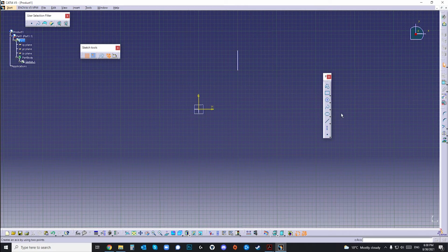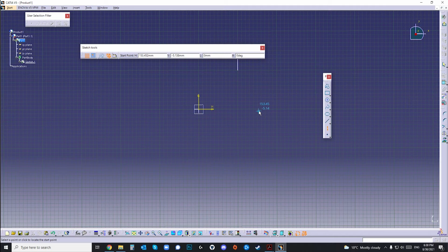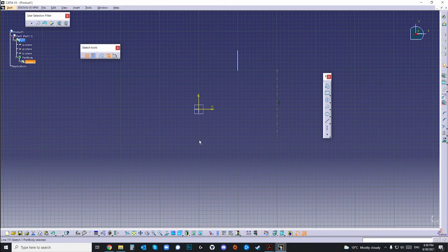In the same manner, you can dimension the axis, and with the point you have just two coordinates because we are in 2D. So if I press for horizontal 50 and on vertical -10 and press enter, there you have your point, which is placed right here with respect to this coordinate system.